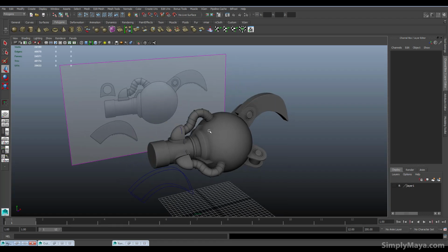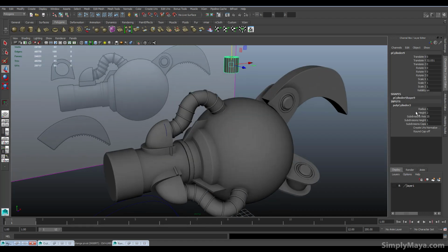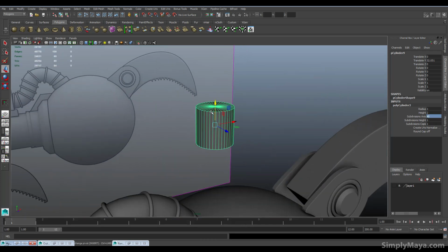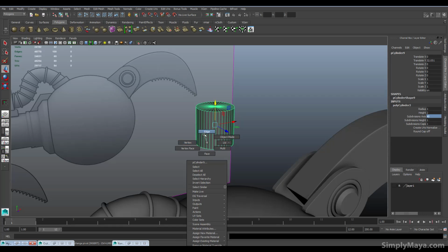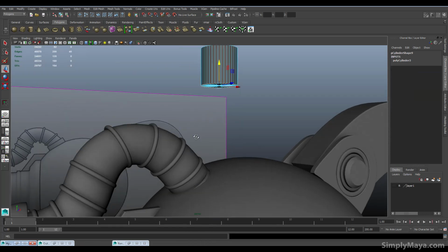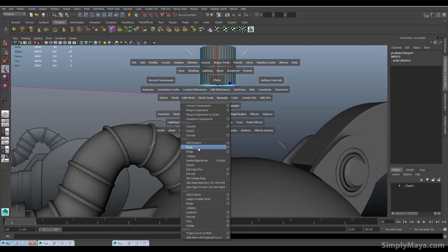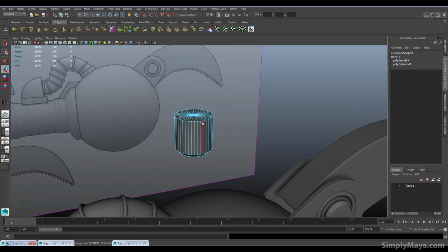So on the stuff I've seen, this has got sort of 8 holes drilled in it. So I'm going to create a sort of Boolean drill bit, and I'm going to take one of these. I'm going to give it slightly more geometry, so I'm going to go to 40. I'm going to put a bevel on the bottom edge, so I'm going to select the edge and bevel it in. So edit mesh, bevel, and I'm going to put a fairly big bevel on, there we go.